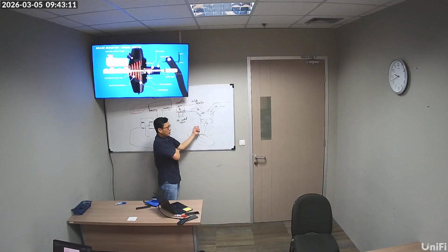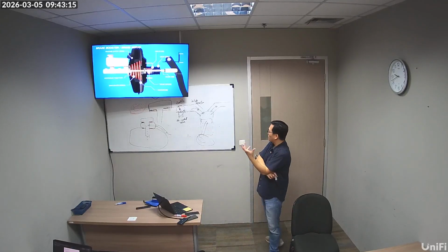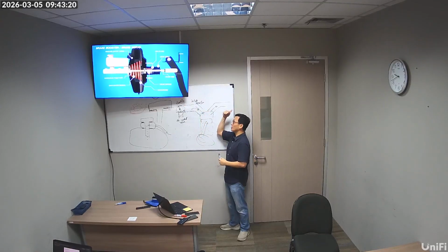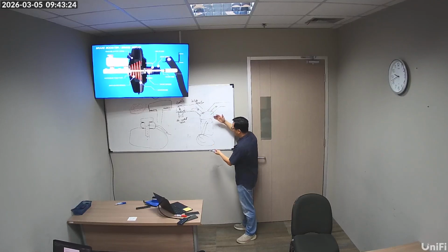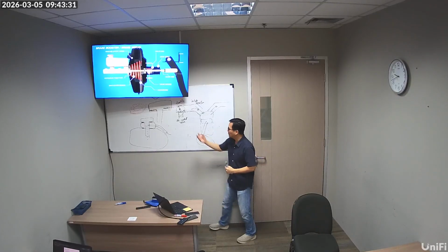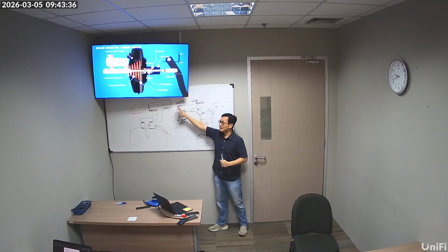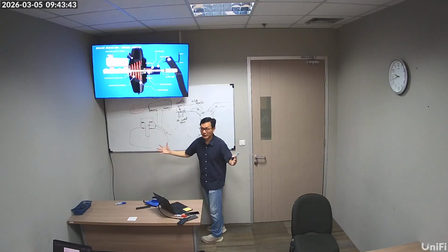Now, your engine is a pretty powerful pump. It actually sucks in a lot of air and gives out a lot of air with some pressure too. And in the process of doing so, it's making power. That's what your engine is. It's a pump. Now, think about a very powerful pump sucking air here. If it's wide open, then there is not much vacuum, because we want this to be opening to the outside air as much as possible.